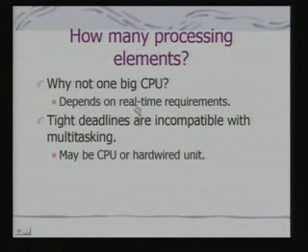But critically, that depends on your time constraints. In fact, if you go back to the example of the camera design that we had considered, we were not able to do the design using only 8051 simply because I had the timing constraint that the camera should be able to take the next snap within 1 second, and I cannot do compression of the image using the 8051 even when I am using additional logic on FPGA blocks.